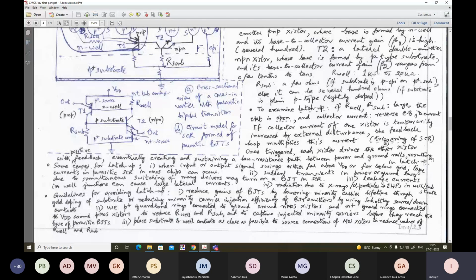Because the bipolar junction current tries to dominate over the field effect current, and also the current can be uncontrolled. So heating will take place and eventual damage can take place.